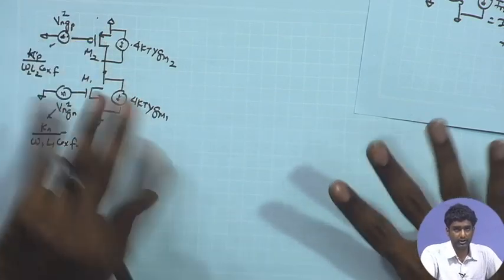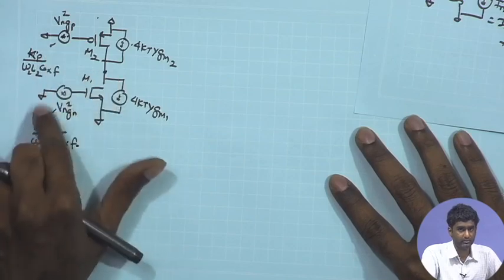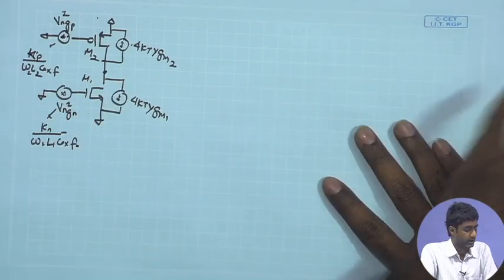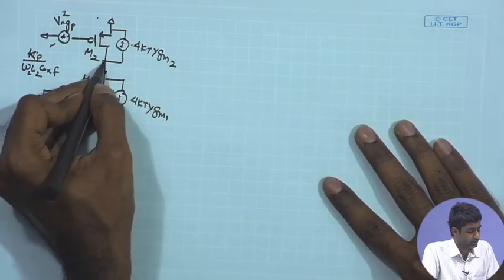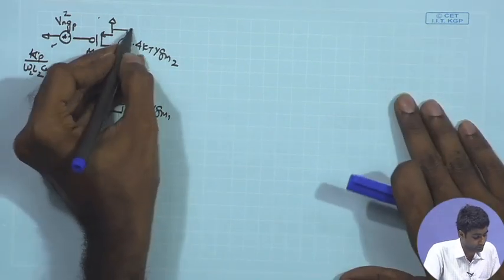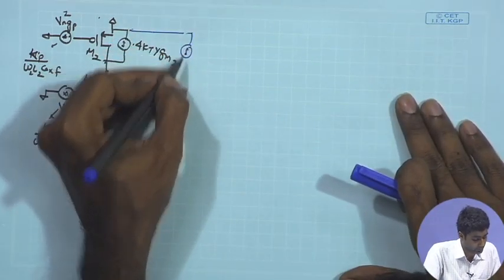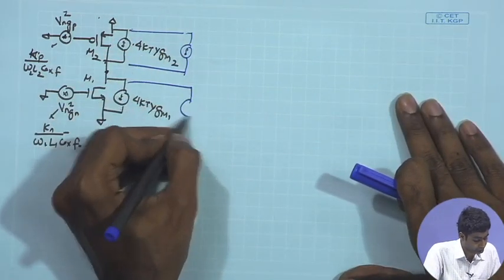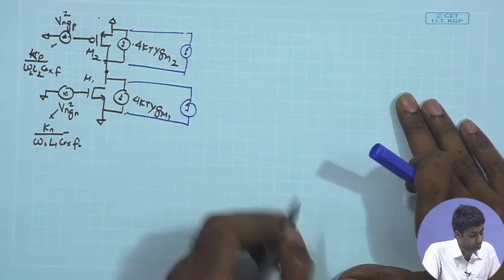For these two, it is clear to see that the gate voltage can be translated into the channel current, and therefore I can write down the equivalent noise current coming because of the gate voltages translated into channel current.